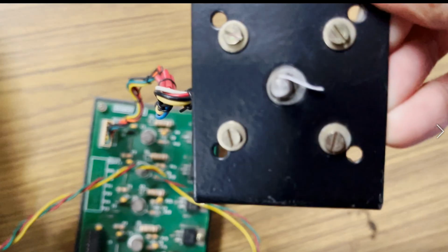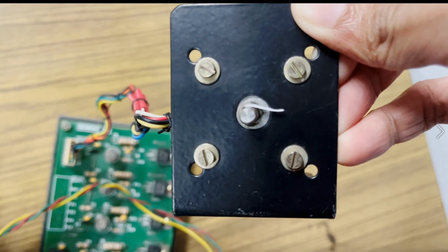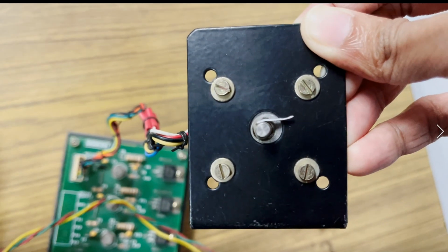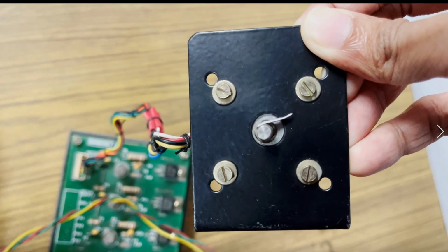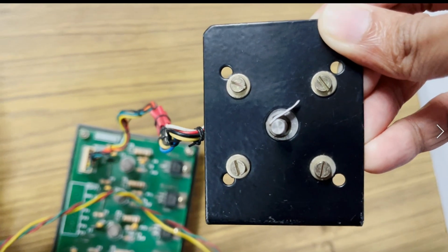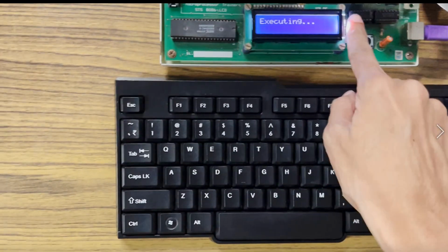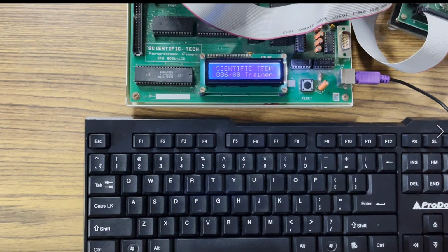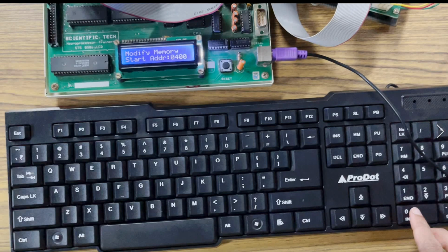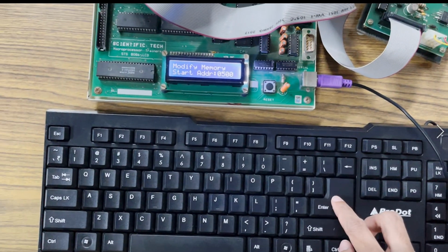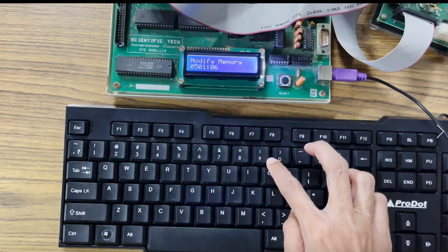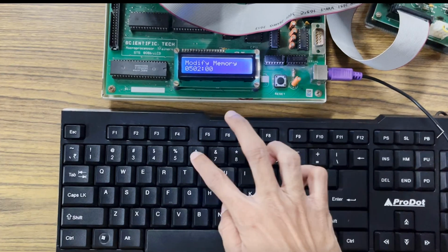We can see that it is moving in the anti-clockwise direction in this example. Now, in order to do it in the clockwise direction, we need to reverse the order of the data we gave before. So, we go to the location 0500 and load the values in reverse order. So, we'll start with 09, 05, 06 and 08.